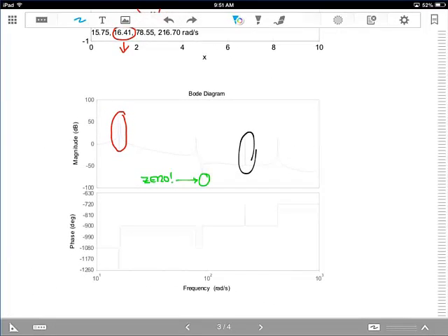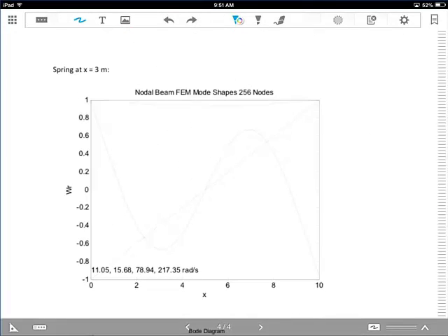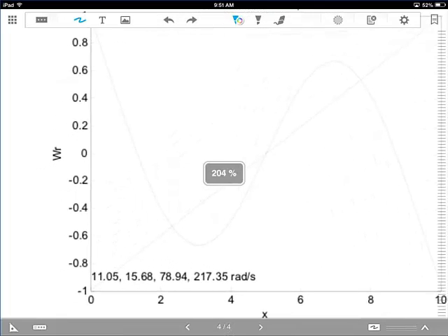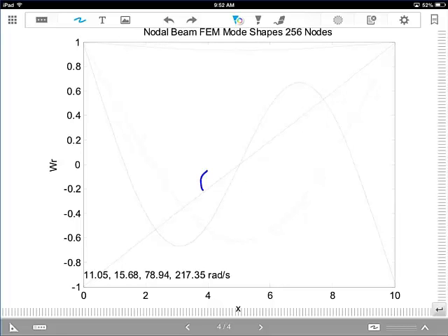So that's kind of neat. All right, I did one last example where you really move the spring in close. The only thing that's different here is that because of the colors, you see that omega 1 or W1 is actually that, and W2 is this. So again, the frequency of that translational mode really hasn't changed very much. The difference is that the frequency associated with that rotation mode has gone down quite a bit, and now they flipped positions.